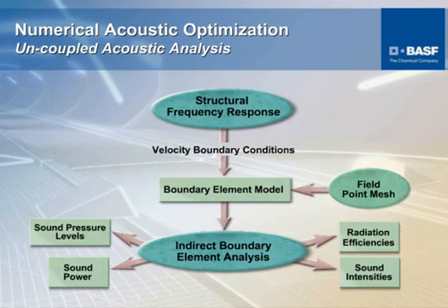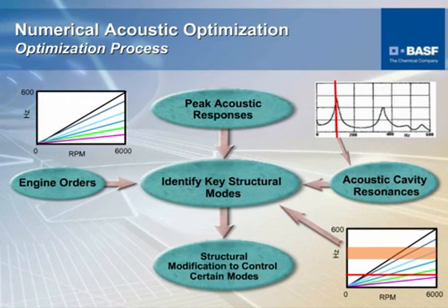So you can have holes and do the analysis. From that you can get multiple parameters such as radiation efficiency, sound intensity, sound pressure level, sound power, and so forth. It's also a very powerful technique to do some numerical acoustical optimizations, we can look at the peak acoustical response.